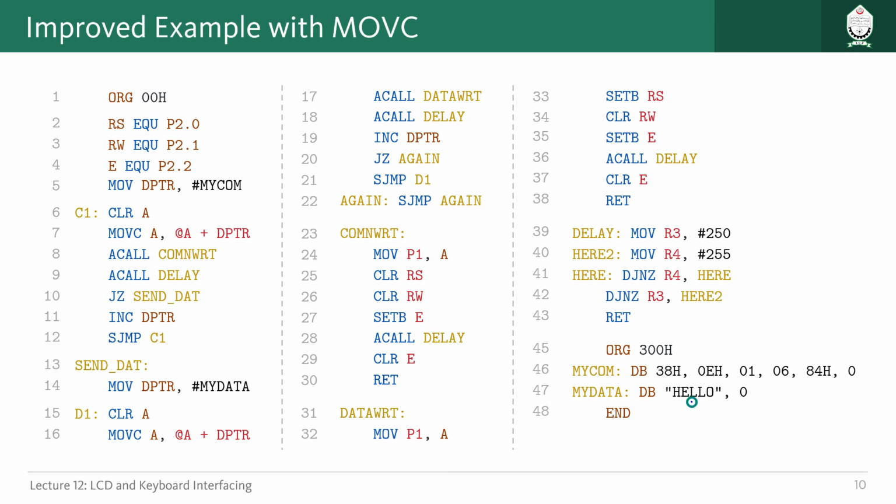If you write it in this way, each of the characters is represented using its ASCII representation, and each memory location will contain one of the characters. So we can fetch them one by one by getting their memory location, right? All of the other things you can see in this code, like command writing, data writing, and the delays, are just like the previous two examples we have seen.